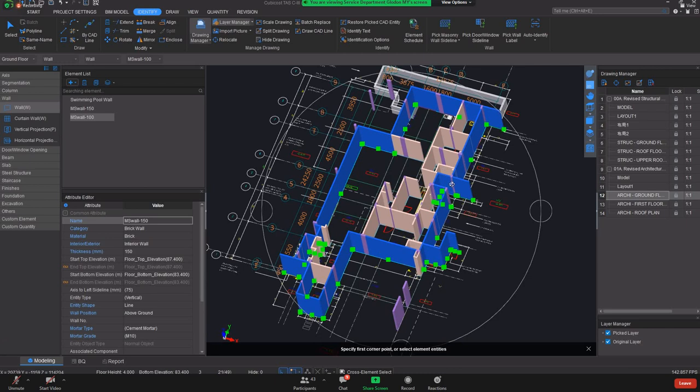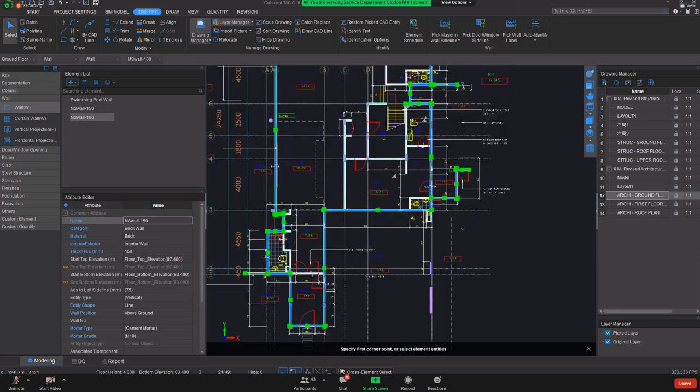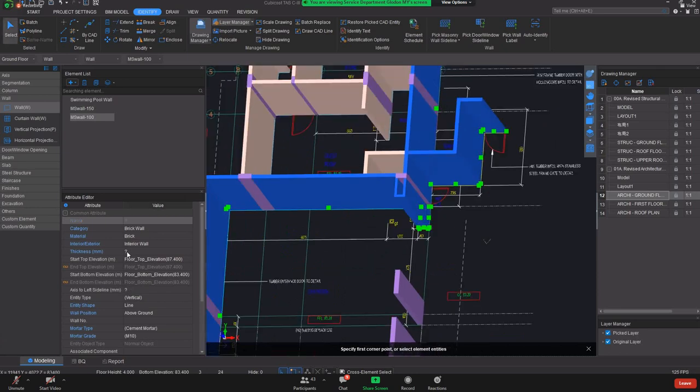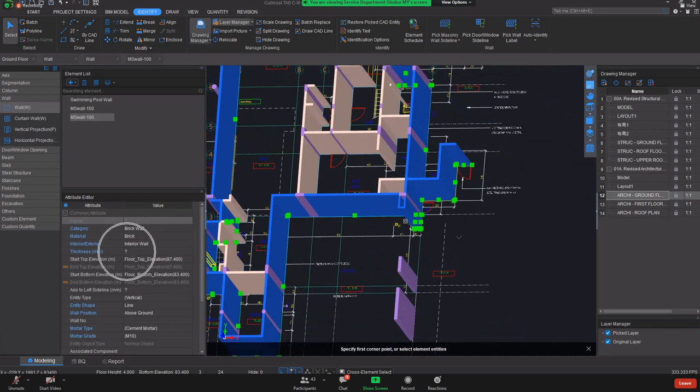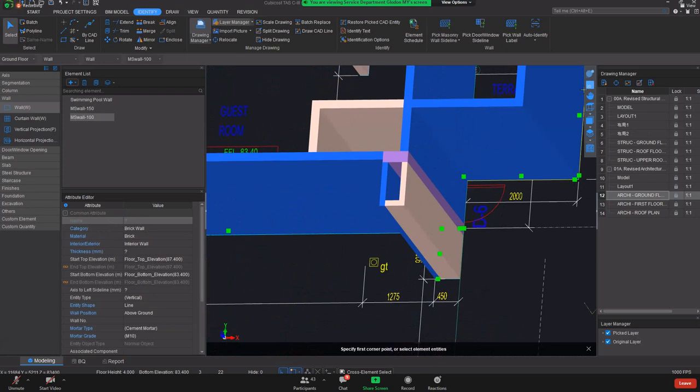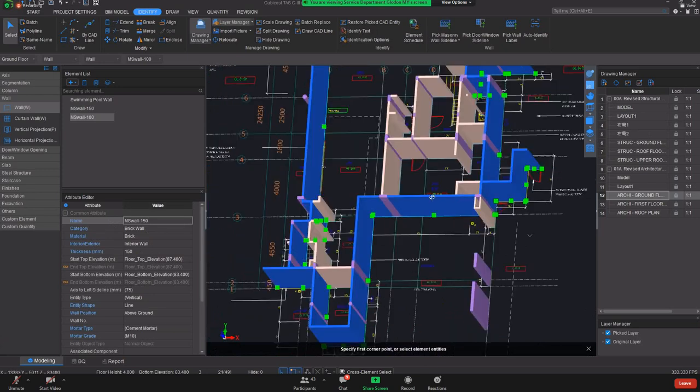If you have already done the break and selected the external wall, there are a few things you need to make clear. The first thing is to remember that we are selecting the 150 mm. If you accidentally select these three parts, there will be question marks in the thickness. So remember, don't select the 100 mm, because that one is 100 mm.